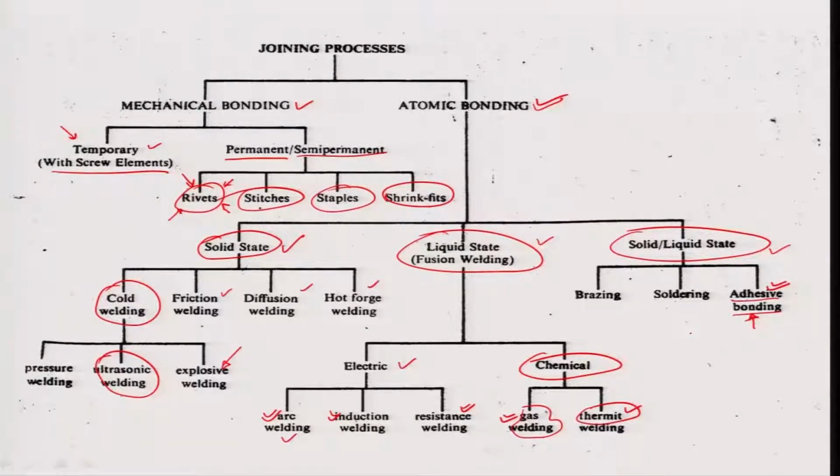You have soldering and brazing, where again the filler material is basically taken to its melting temperature, and it generates some kind of local melts in the periphery of the weldment, and there is some degree of diffusion into the welding zone in the periphery, which results in again resolidification and joining between both the solid members. Okay. So, these are all examples or classifications of different joining processes.